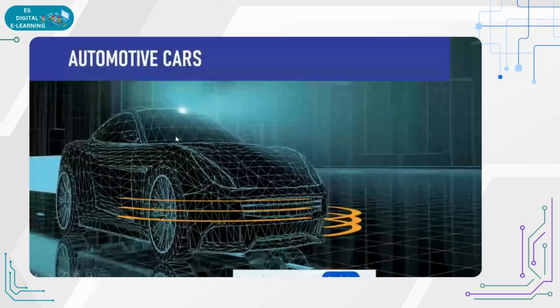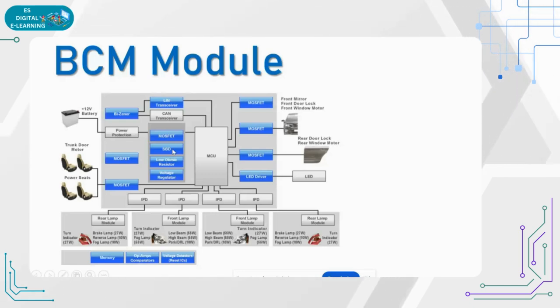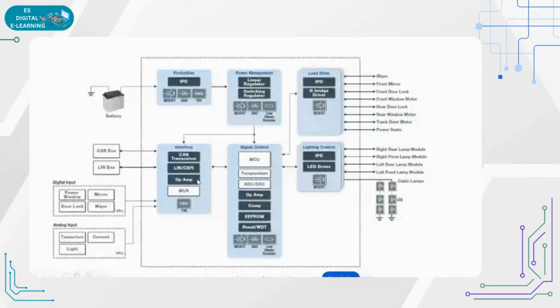Okay, so here is the body control module. It is one master controller. Usually for low-end cars it has one single controller that additionally controls the doors, lighting, seat control, some of the LED lamps, and the indicators. Just to be aware of the body control module, we look at what inputs and outputs will be connected. And here is the internal block diagram of the same.